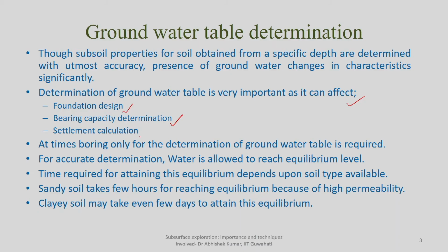The third point is settlement calculation. Once the bearing capacity or load settlement curve changes because of the presence or absence of water, that will also give us an idea about the total settlement or differential settlement in actual ground conditions. So, as important as it is to determine the subsoil properties accurately based on field investigation and laboratory investigation, equally important it is to determine the groundwater table.